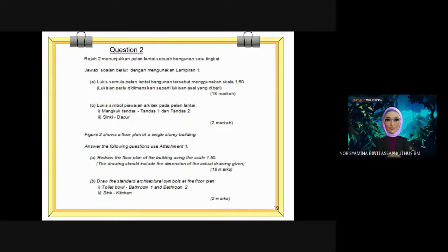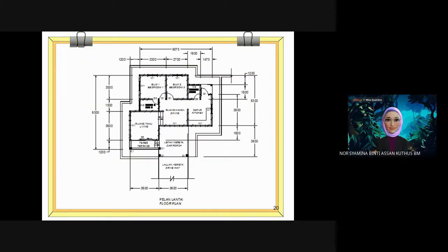Alright. So for example, let's say the question gives you a floor plan to draw with the dimensions given in your original drawing. What you need to remember for your floor plan is that you will be drawing according to the scale, but you will reduce the scale, like 1 to 100 or 1 to 50, depending on the size we want to draw and the size of the paper we are drawing on. If it can fit into 1 to 100 scale, then we can draw. But if it can also fit into 1 to 50, that is fine too.